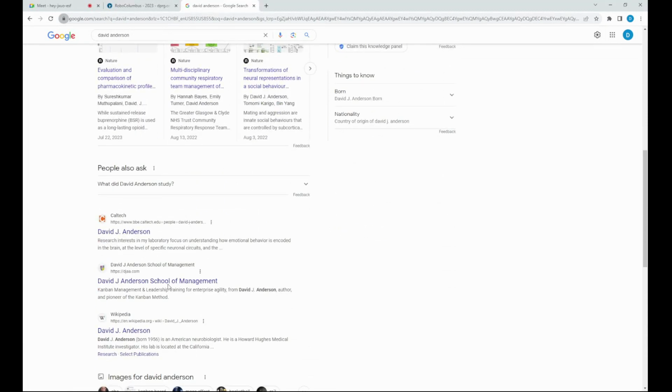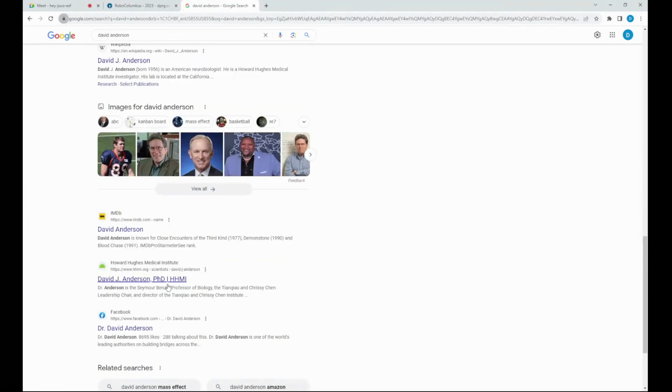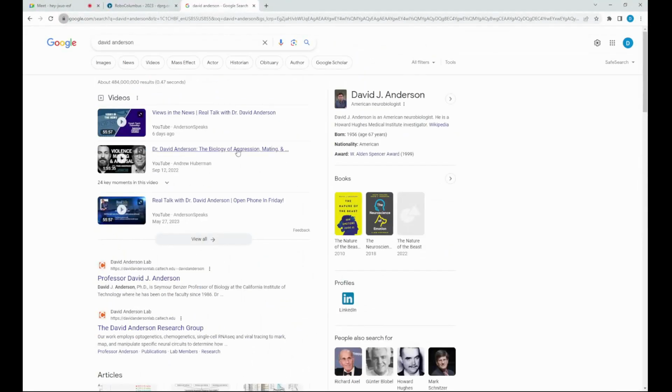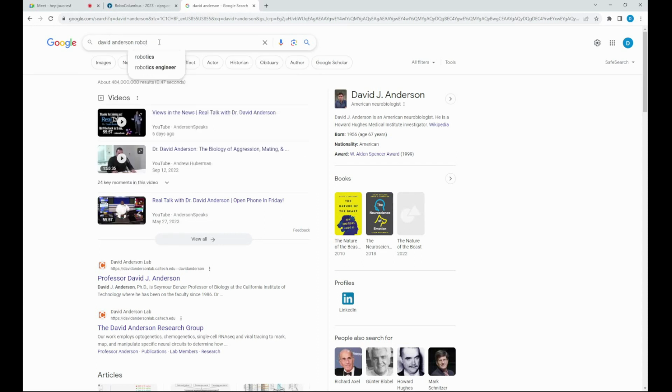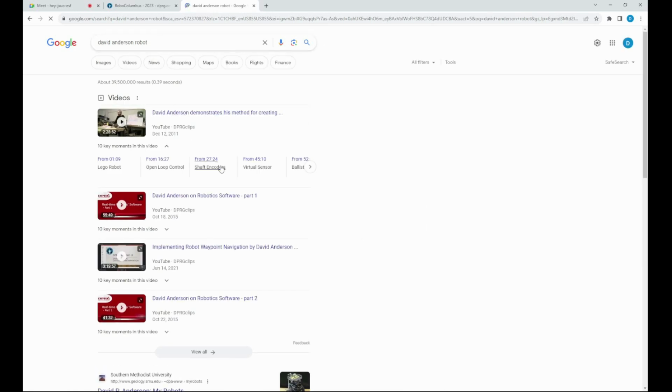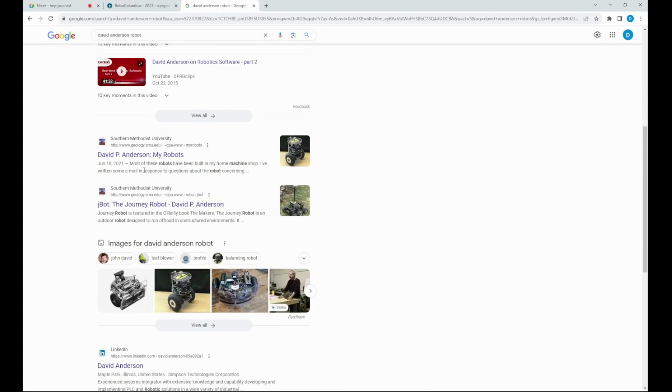Yeah, okay. And for the IMU, are you reading that just in your loop, so every 50 milliseconds, 40 milliseconds, whatever? Or are you reading it off of an interrupt? Let me go to that other picture to refresh my memory. Okay, so the IMU, I'm reading that in a small piece of Arduino code here. Also using PlatformIO, and it's just doing it in the loop, I'm pretty sure.